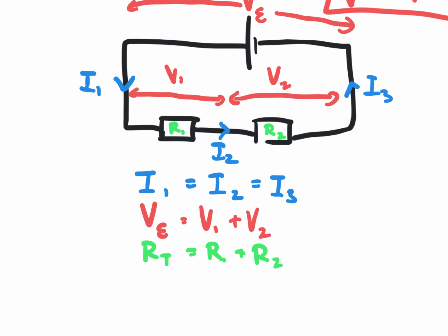So these are the rules in a series arrangement, right? Where in the main path, current will always be the same. It will always be equal. Whatever current I have here will be the current here and the current here in the main path. When I see things in series, from point A to point B, so to speak, I would know that the potential difference, if across the entire thing, is, let's say, 6 volts, this plus this will be equal to 6 volts. It adds up when I go across in series. And how do I find total resistance?